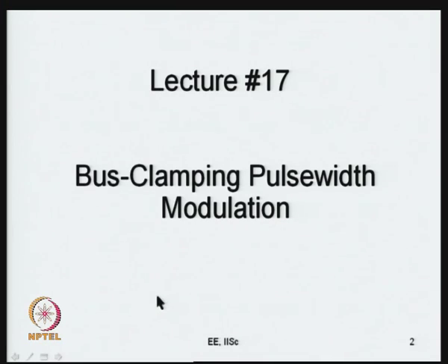So, for voltage source inverters, again we looked at many of these in previous lectures. We looked at sinusoidal modulation, we looked at selective harmonic elimination and such low frequency techniques, and finally over the last 2-3 classes we have been looking at pulse width modulation, which assumes a fairly higher frequency. That is, if you have an inverter, the inverter switches at a certain frequency which we call the switching frequency. Sometimes the switching frequency is a low value, that is, the ratio of switching frequency to the fundamental frequency is not very high.